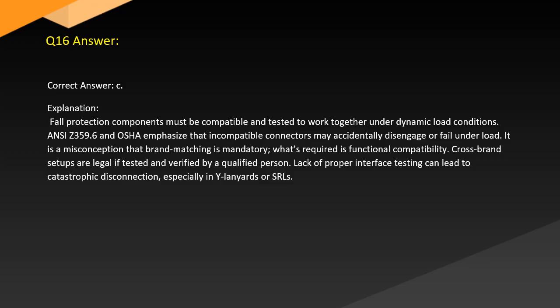It is a misconception that brand matching is mandatory. What's required is functional compatibility. Cross-brand setups are legal if tested and verified by a qualified person. Lack of proper interface testing can lead to catastrophic disconnection, especially in wire lanyards and SRLs.